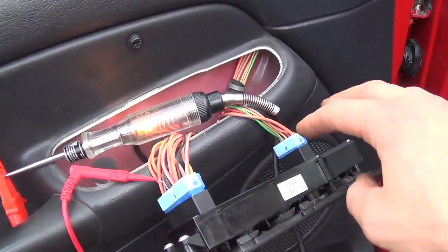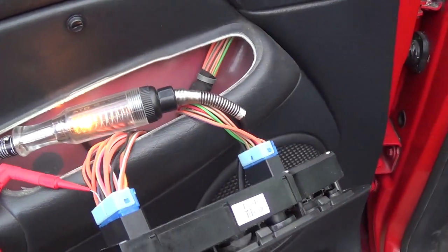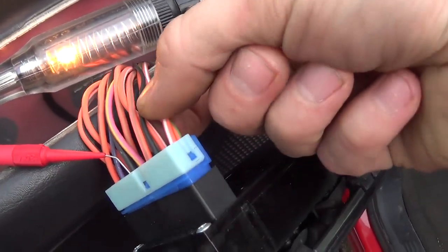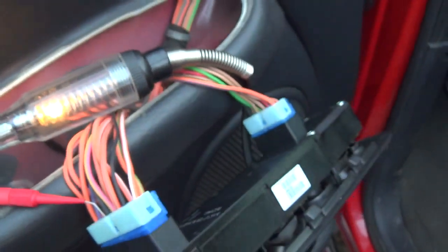We have a bad connection here to our lockout switch wire, and we have a broken wire, this orange and white on pin 7, is it pin 4, going to our left rear door. So I'm going to see if you want me to go any further. If not, thanks a lot for watching. That kind of kicked my butt, but anyways, sometimes it's better to focus on one thing and not worry about taping, but I really wanted to bring you along, so we'll see where we go from here.